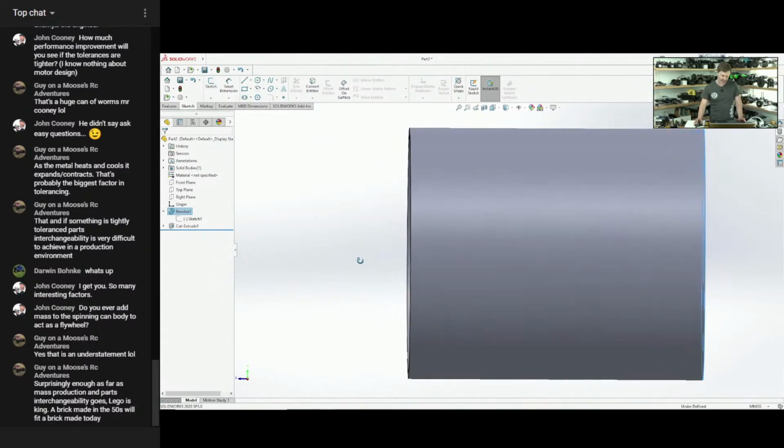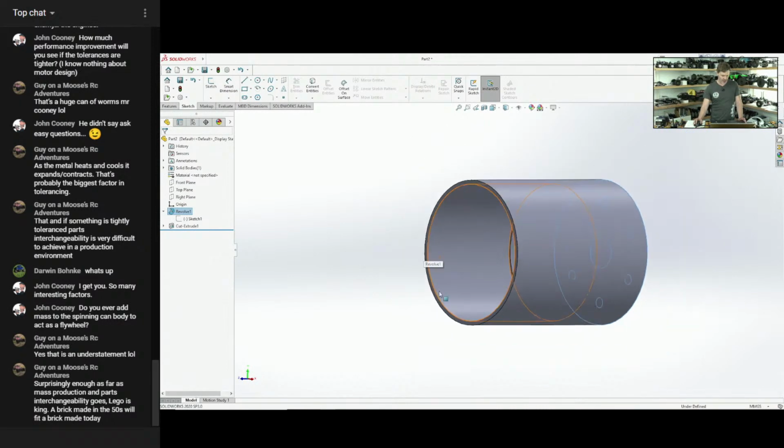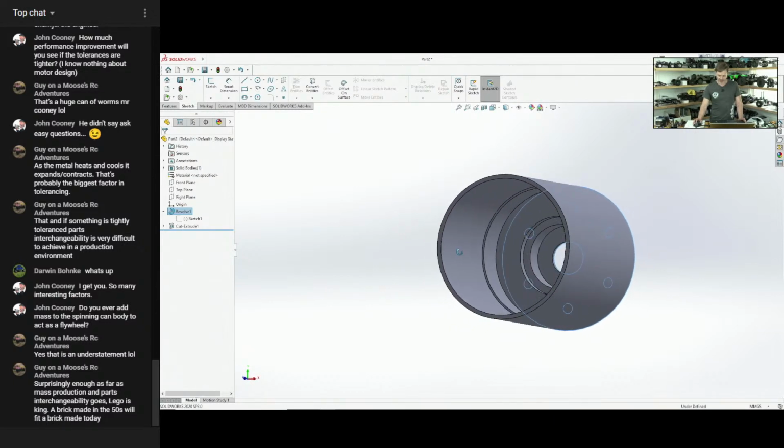If we have, let's say, too loose of a tolerance here where the stator goes in, we want it to be a slip fit, but we don't want it to be too much of a slip fit. If it's, let's say, half of a thou, 5/10,000ths of an inch, that should be fine enough for horseshoes and hand grenades. I would prefer to see more like a 2/10,000ths of an inch slip fit. That way we don't have a lot of variation in our stator. But stators a lot of times are going to be undersized and oversized just a little bit, in a way where you can't have it too tight, or else some of them just will not assemble, or you'll end up damaging the stator when you try to press it in, and it's just kind of a big hassle, of course.